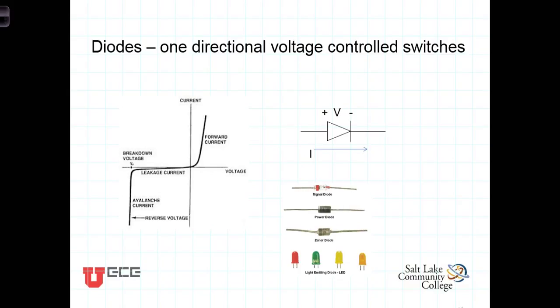Now the voltage-current relationship in diodes is a little bit complicated, certainly more so than in the devices that we've seen up to this point. What this is meant to represent, and we've got the voltage along here and the current along this axis, we see that it takes that junction voltage amount, an external voltage on the order of the junction voltage itself, must be applied to overcome that junction voltage and allow current to start to flow.